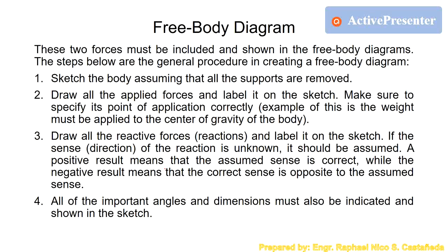These two forces must be included and shown in the free body diagram. So these are the steps in creating a free body diagram. The first one is to sketch the body, assuming all the supports are removed. Next, draw all the applied forces and label them on the sketch.